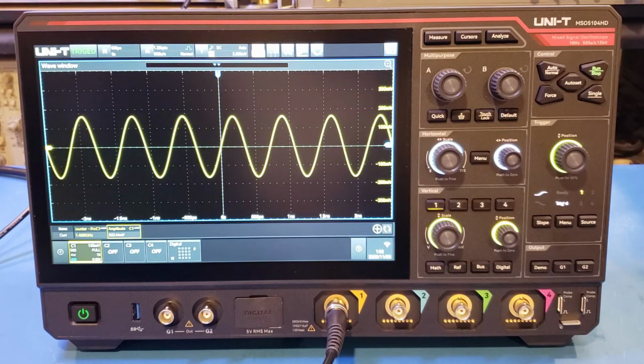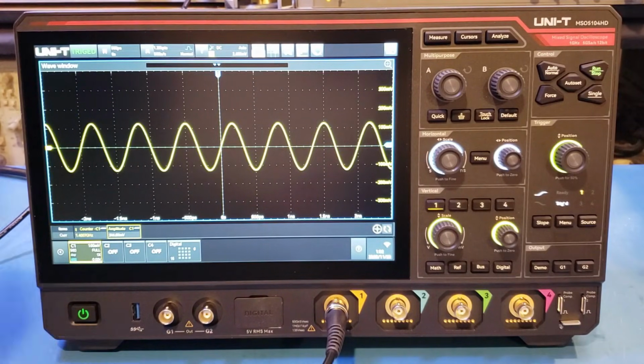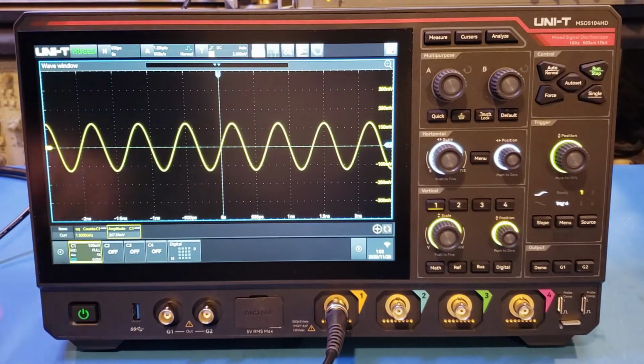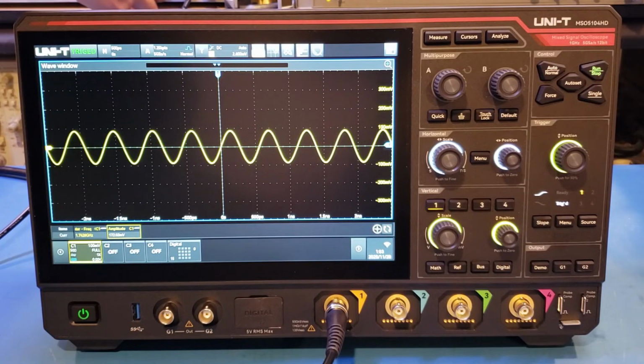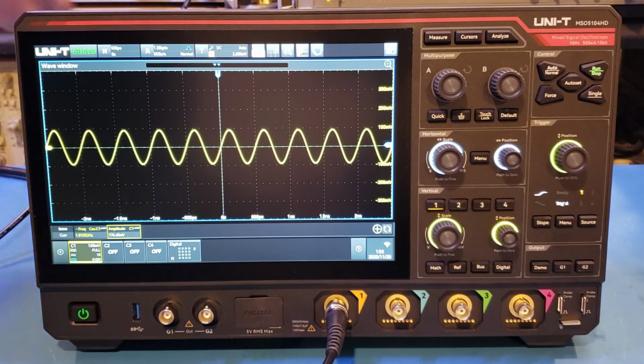Now let me keep increasing the frequency and just see what we get on the scope. Of course, it's already below the 3 dB bandwidth, but we should be able to see whether or not we're actually able to capture that signal. Given the 5 gigasamples per second sampling rate, we should be able to capture quite a bit higher. So let's take a look. So now I'm doing 1.5 gigahertz. And you can see we have no problem detecting that 1.5. The amplitude, of course, dropped quite a bit. So 1.6, 1.7, 1.8, 1.9, 2 gigahertz.